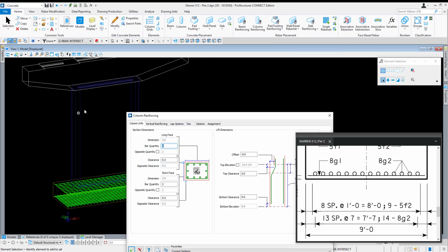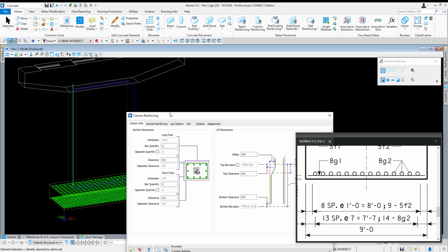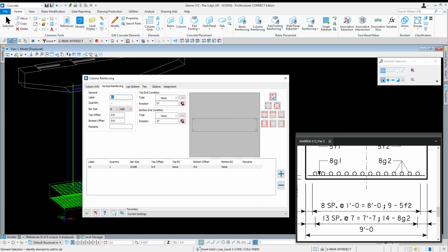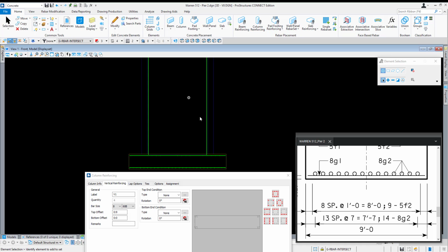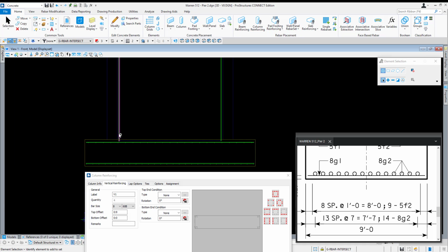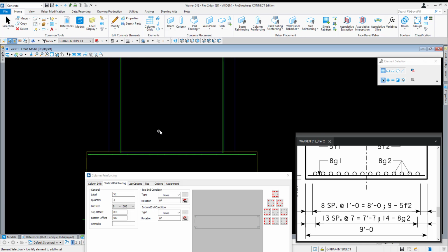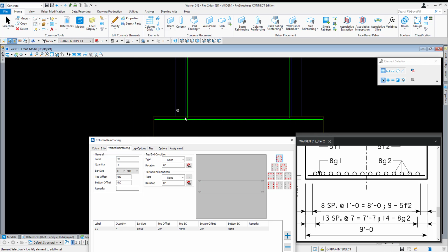Just to see what happens whenever I try to model column reinforcement within this next solid here, I'm going to go ahead and just select it. So right now I've got 1 bar in there. Let me see, I'm going to get at least the 4 corners in. That way I can see what it's recognizing as the outside of column. And it looks like it's actually going to work to our benefit in this case, because it seems as though it's seeing just the interior rectangular solid, not the half-cylinder sides, as the solid element. I'm guessing those were combined after the centerpiece was modeled, so the program's only really viewing that center geometry.